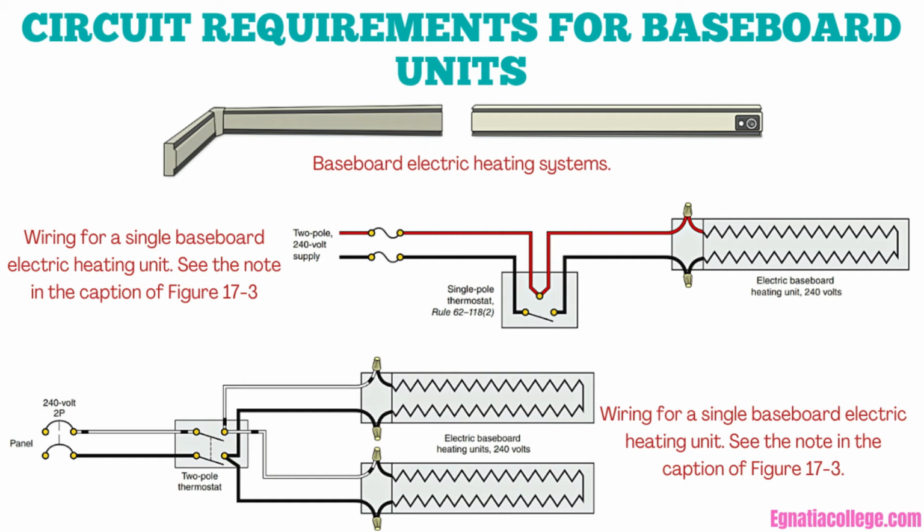A second 2-wire cable runs from the thermostat to the junction box on the heater unit. The proper connections are made in this junction box. Most heating unit manufacturers provide knockouts at the rear and on the bottom of the junction box. The supply conductors can be run through these knockouts, using proper connectors for their wiring method.